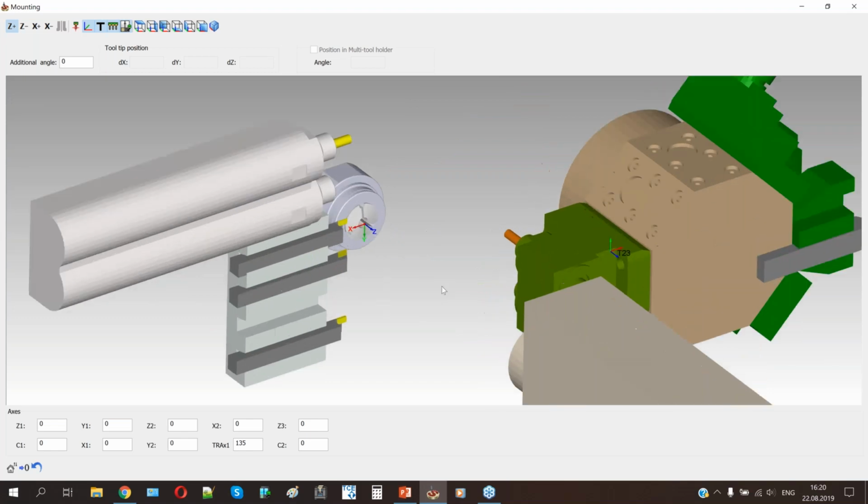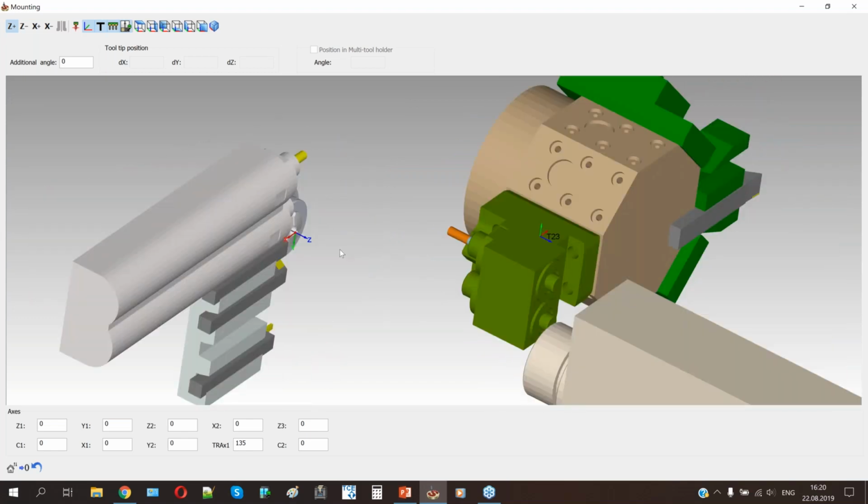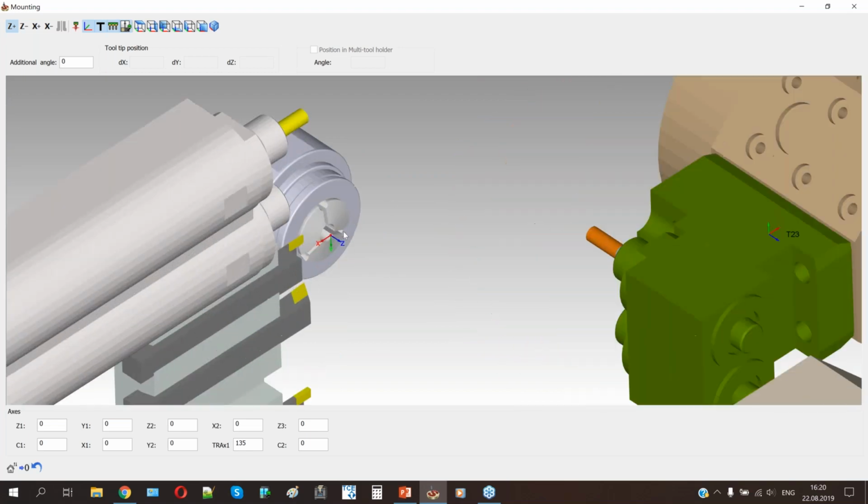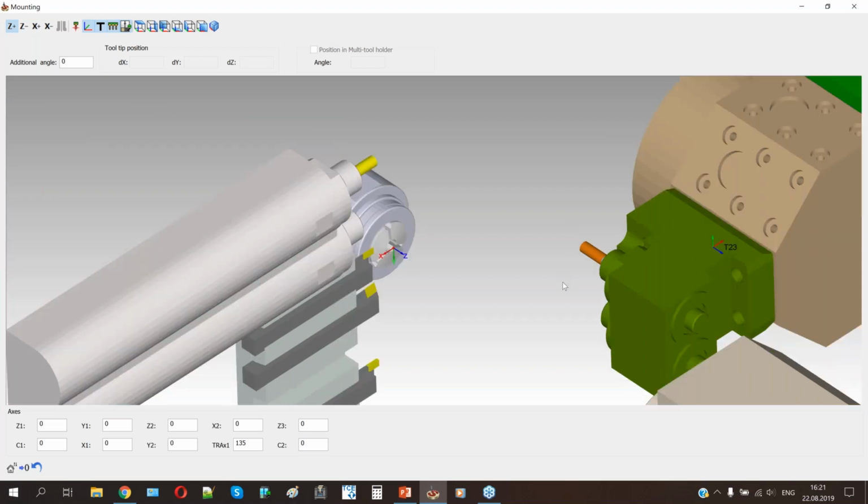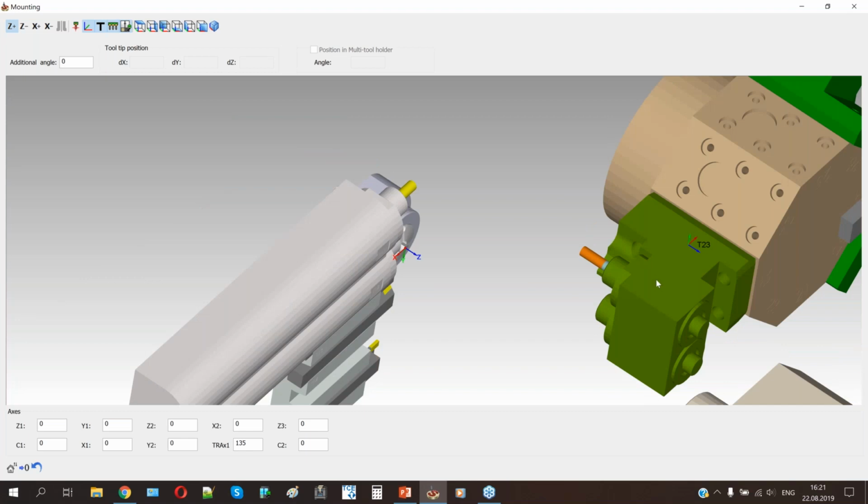This structure lets us apply different configurations for machining on the main spindle. We can machine the part with the Z1 axis and X1 axis. It's machining like we usually perform on any Swiss type machine. We can also perform it by pulling out our stock, fixing it, and operating with the Z2 axis and turret.